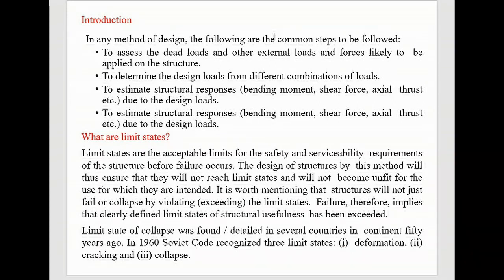This method consists of two different types of limit state. That is, the ultimate limit state, which consists of strength, overturning, fatigue, sliding and so on. And the second one is the serviceability limit state, which consists of crack width, deflections, vibrations and so on.